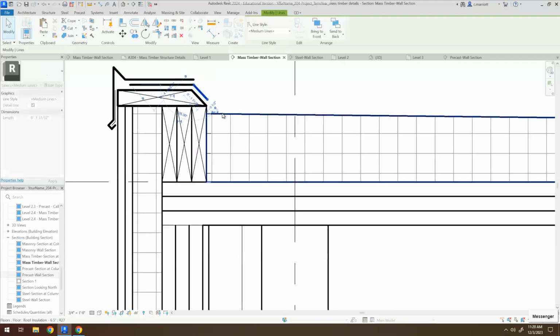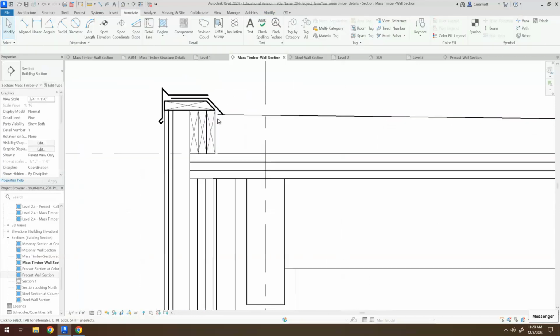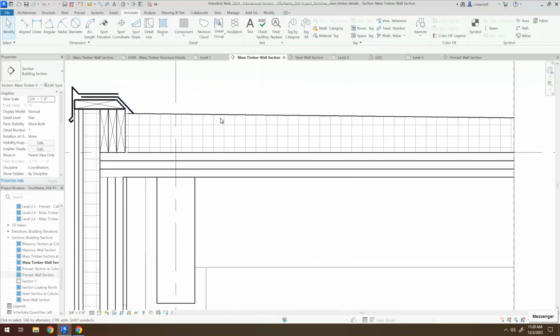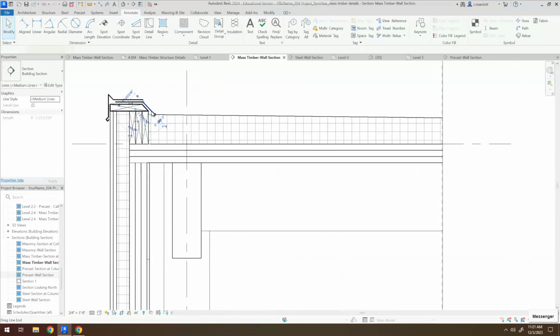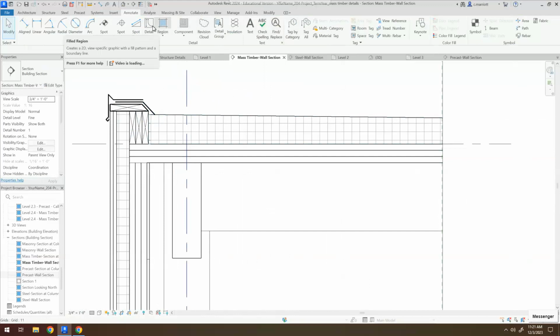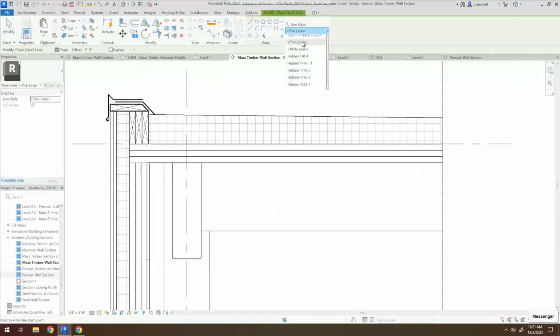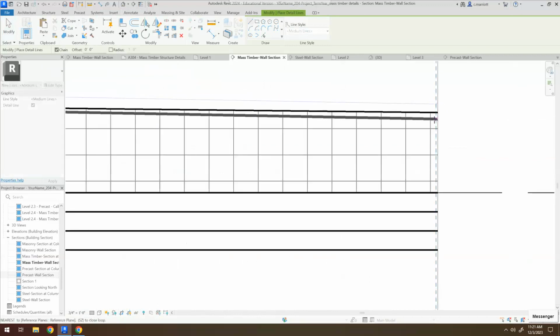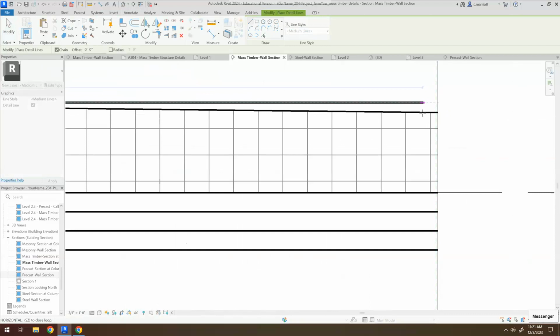All right, we're going to need to bring in a membrane line. So it will be a little bit heavier than this one. So this is done with a medium line type. So I'm just going to add another detail line. This one, I'll make it a little thicker, and we'll bring it down here. Is it going to let me snap to that point? I probably need to adjust the object snaps for that.